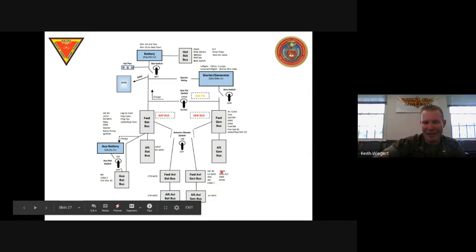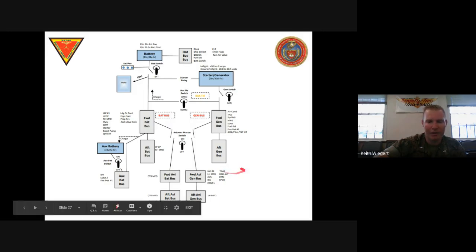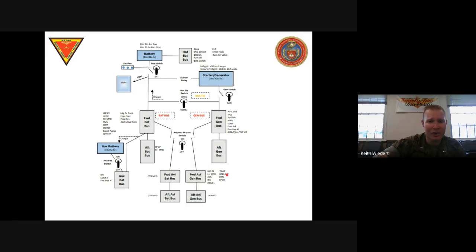I've got my TCAS, my traffic collision avoidance system. Basically lets you know where anybody who's squawking anything is in relation to you, as long as they're within range, right? That's your TCAS there. You got your radar altimeter. Radar altimeter is going to come on automatically below 2,000 feet AGL and just read out on your PFD and let you know how far you are above the ground.